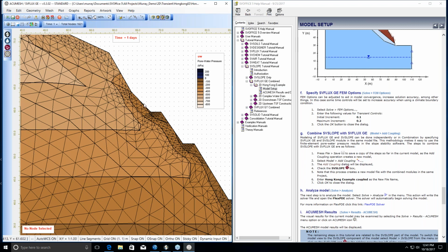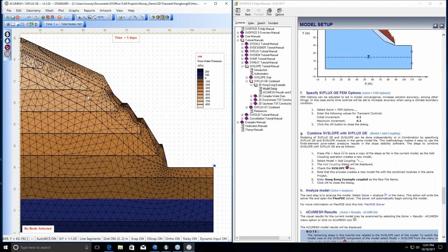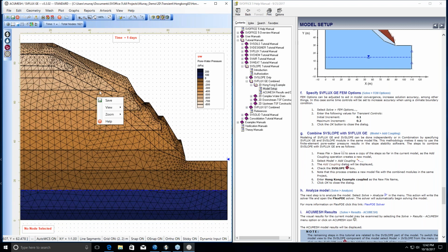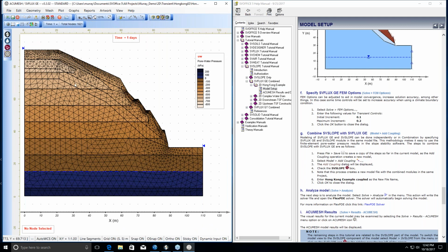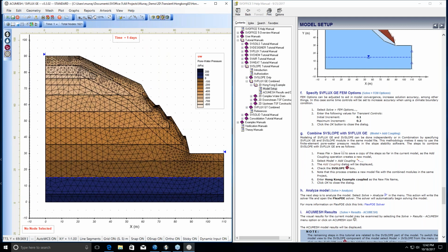We're applying a flux and loading the numerical model with a flow, and therefore you need a little bit extra mesh density along the upper surface. We can see that happening automatically in the solver. That's one of the nice features of running with FlexPDE: there's automatic mesh refinement, and it handles that for you.